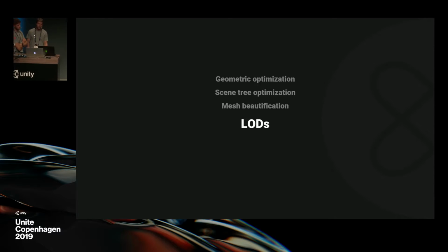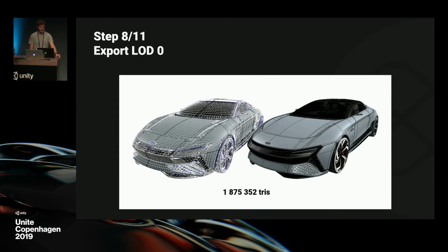So now that we are done with mesh purification, we want to create LODs, to go to Unity, of course. So we want to create 3 levels there for our car model. At this step, high-resolution LOD0 is ready. It's the model we've prepared so far, and it's made of around 2 million triangles. But to finalize this LOD, we just trigger a quick repair mesh that we showed before. We do that because parts were merged together in previous steps, so we need to fix some potentially disconnected edges in the final meshes.